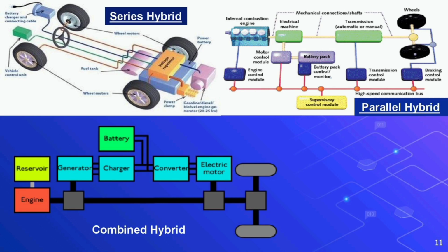electric vehicles. Coming to the parallel hybrid, it gets around these problems. In this case, the IC engine is connected to both the wheels and an electric motor. It gains from regenerative braking, and at low speeds, the electric motor can drive the vehicle without the IC engine. Parallel hybrid systems tend to be much simpler, easier, less costly and considerably less complicated to install.